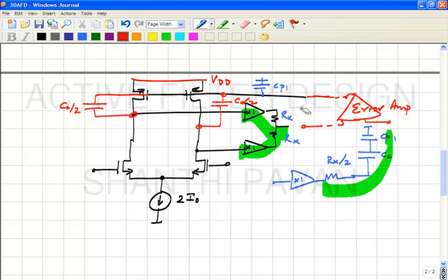As far as common mode is concerned, now you see that if I yank both the sides up, the voltage at the gate of the PMOS transistor rises up instantaneously. However, as we noted before, this has the problem that Cc by 2 now also starts to appear in the differential mode equivalent.